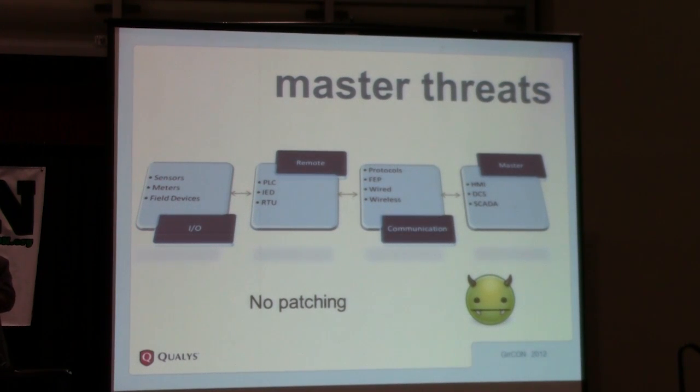And so are patches. So if, for example, your system runs Windows, Microsoft releases a patch every what? Once a month, right? Patch Tuesday, everyone knows about Patch Tuesday. And that means you have to patch your Scada system every month. Now what happens here is you have two vendors here. One is your operating system vendor, which could be Microsoft or Linux or whatever, and one is your Scada software vendor.